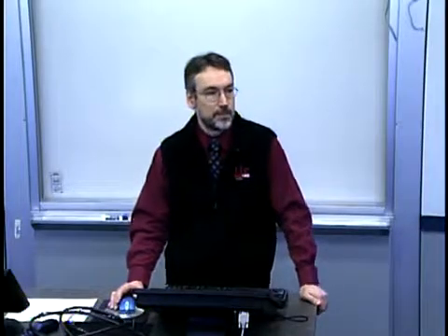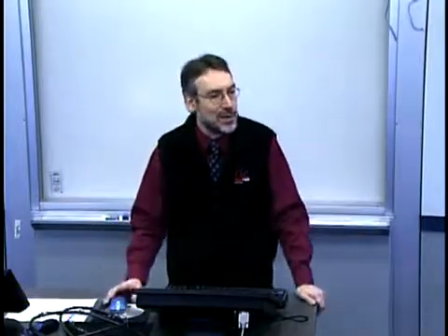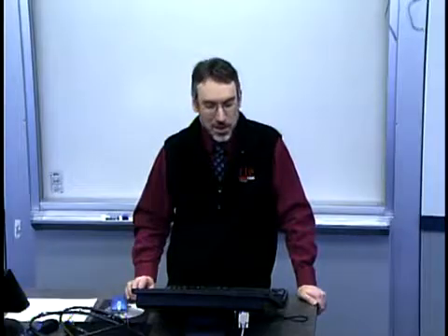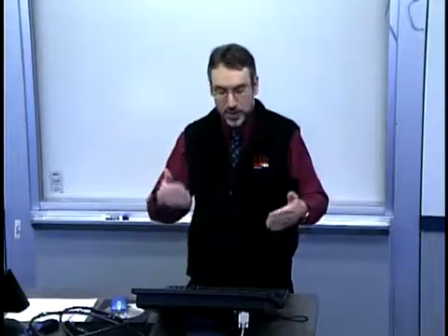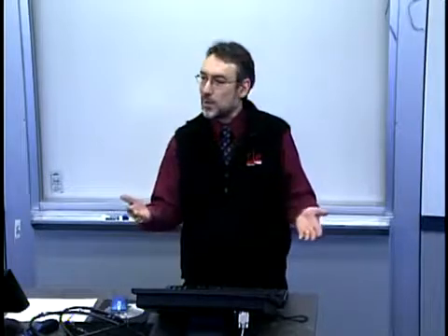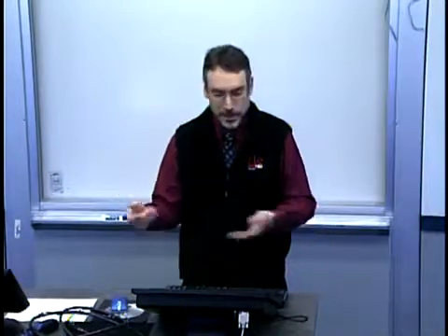What else do you see? No. The data is sort of drifting up over time. Okay, so it looks like there might be a long-term trend of a drift over the number of runs. What might lead you to think that would be physically reasonable? Probably, I mean, for a few readings the tool doesn't wear that much, but... Right. So if the tool wears, or there's some long-term change in the state of the equipment, that's often the source of these long-term trends, right?